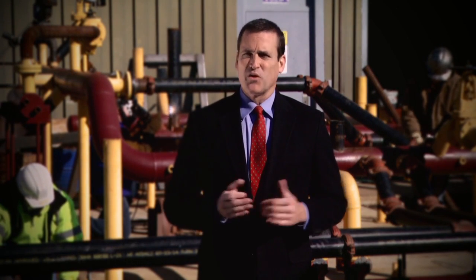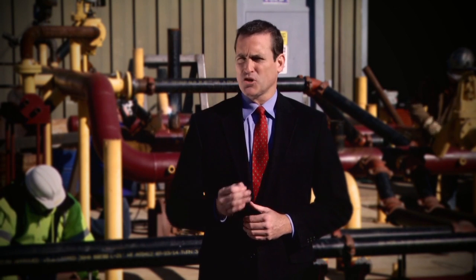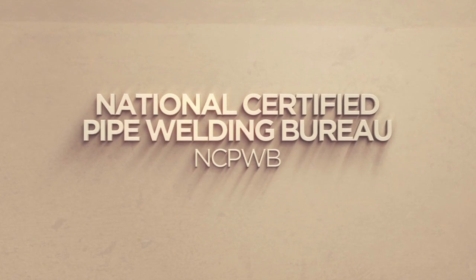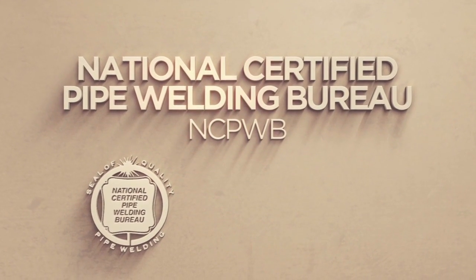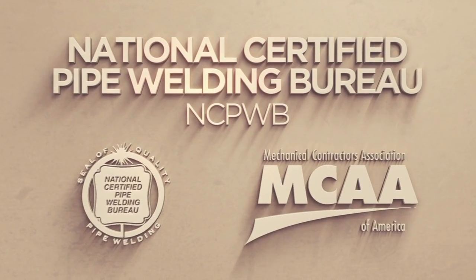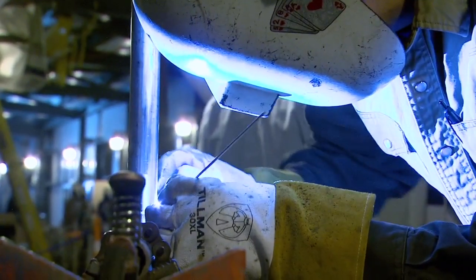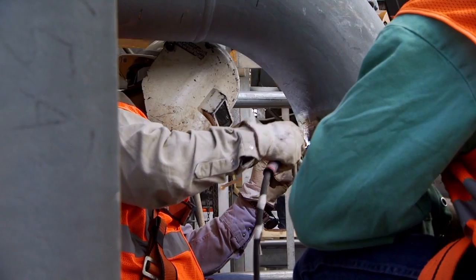To ensure the contractor has the required procedures in place for critical activities such as welding and brazing, the engineer should have the contractor submit the procedures they plan to use and personnel qualification records for review and approval before welding or brazing starts. Contractors who are members of the National Certified Pipe Welding Bureau, NCPWB, a subsidiary of the Mechanical Contractors Association of America, not only have welding procedures that are fully compliant with the B31 codes, but their welders and supervisors have been trained to follow those procedures.